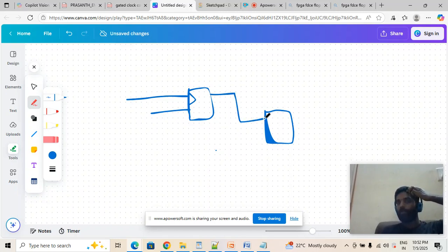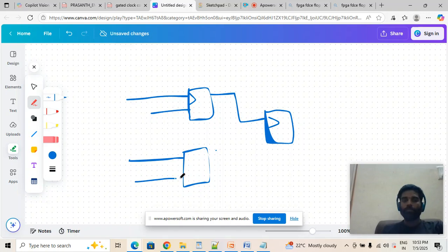It will go and act as a clock here. Earlier we saw it with respect to gates. Now we are seeing it with respect to the register itself. This will go and act as a clock here. It's again a derived clock kind of thing, right? So how do we tell the tool how it gets implemented if you apply the clock gating in this place? For example, if you apply the clock gating in that place, I expect my clock to be connected here, and this is my input, right? So I take my input here, and this is my output.